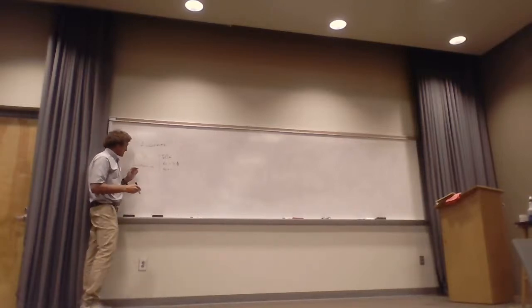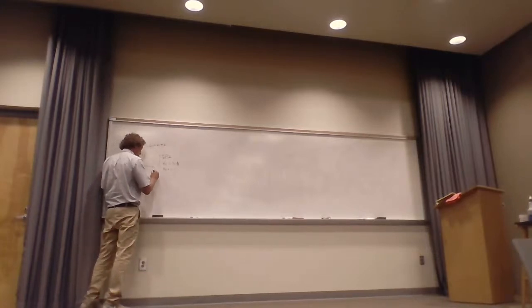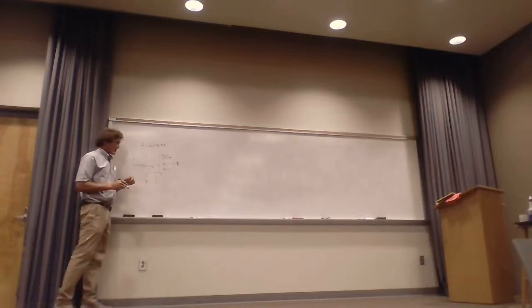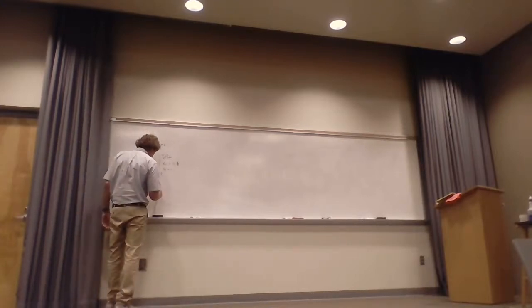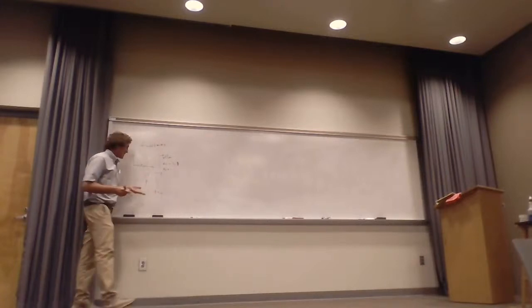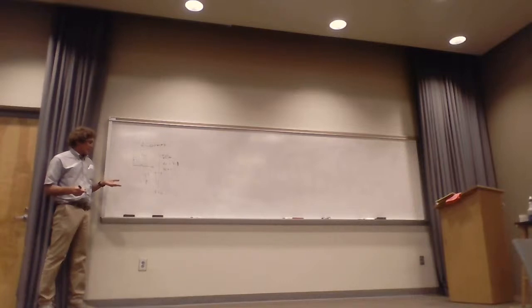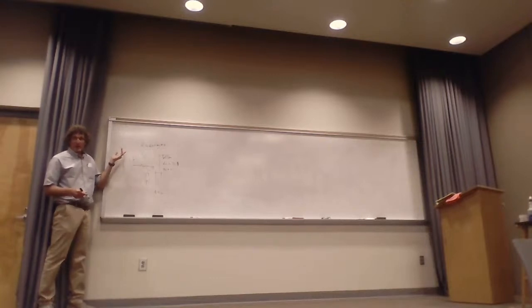So the thing about this is we need the reflection and transmission coefficients at the boundary. Unless there's a good reason for not doing it, you always let the boundary be at Z equals 0. Normally you have EX up here, but I put EY because X is going into the board.